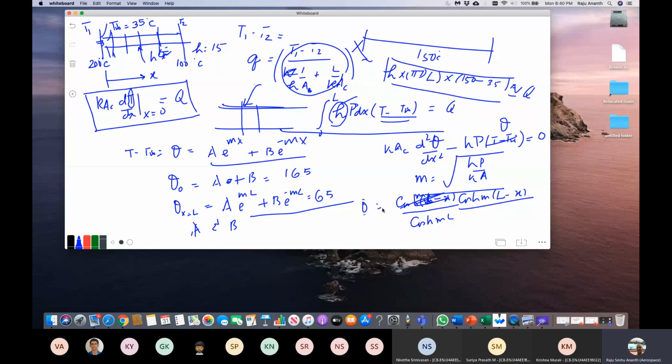So that is theta. So this assumes at x equal to L, d theta over dx is 0. You can clearly see that. Sinh m(L minus x) at x equal to L has to go to 0. So anyway, this will be satisfied with this solution.